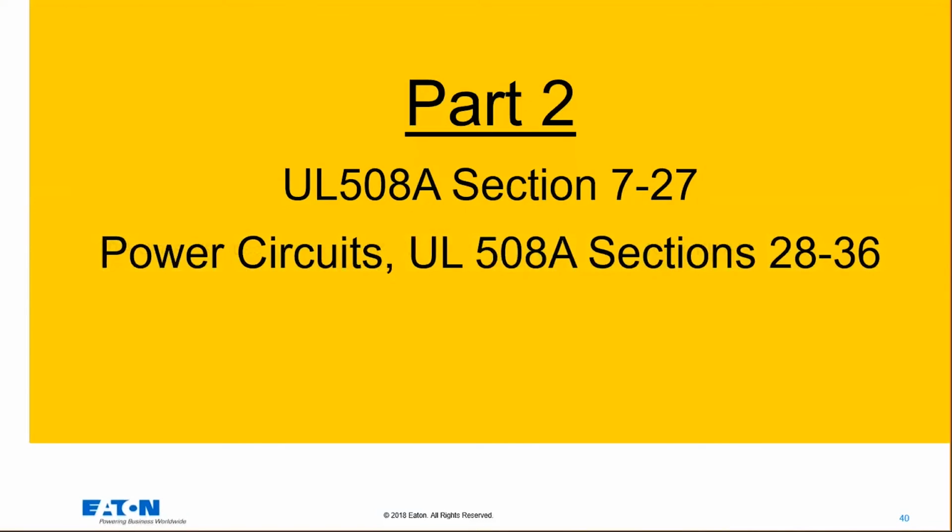If we call Bussmann fuses on the application itself, can we at that point use your tables, or do we always have to go by 4.1? If the manufacturer calls for a certain fuse, then you'll need to use the manufacturer's recommendations for that. Many times when you're looking at drives and other devices, they may spell out an actual fuse to be used. So you do want to look at the manufacturer's recommendations, especially on drives and those kinds of things.